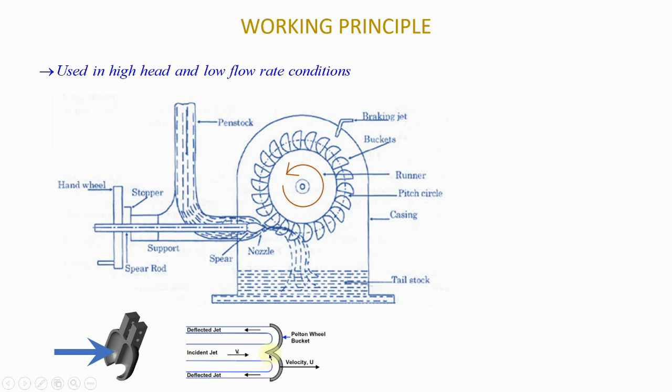And as you can see, you have this split here to split pretty much the jet of water. Some of it will go in that direction, and the other portion of the jet of water will come this way, okay? And so if you see in this particular figure, the jet of water is deflected at an angle of 180 degrees because it was coming horizontally this way, and then it returns in the opposite direction but still perfectly horizontally. So if you try to measure the angle between this and that, it is pretty much 180 degrees.